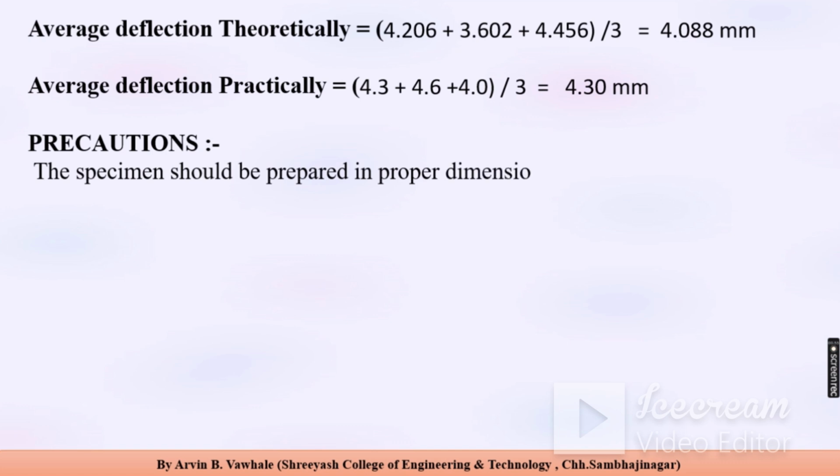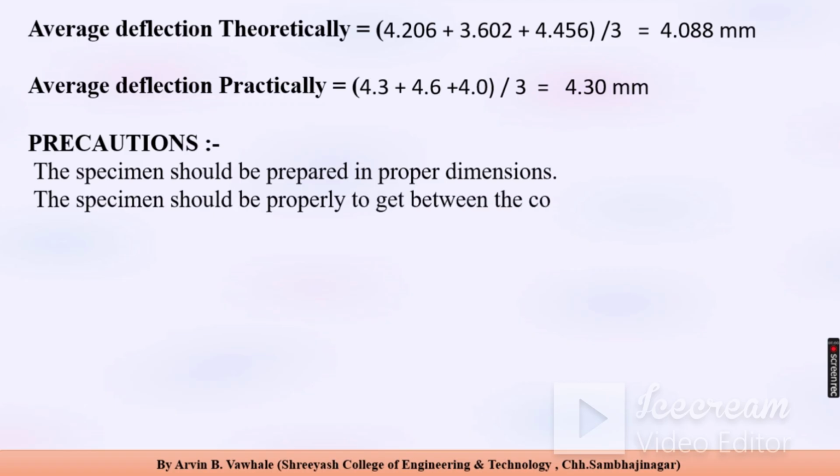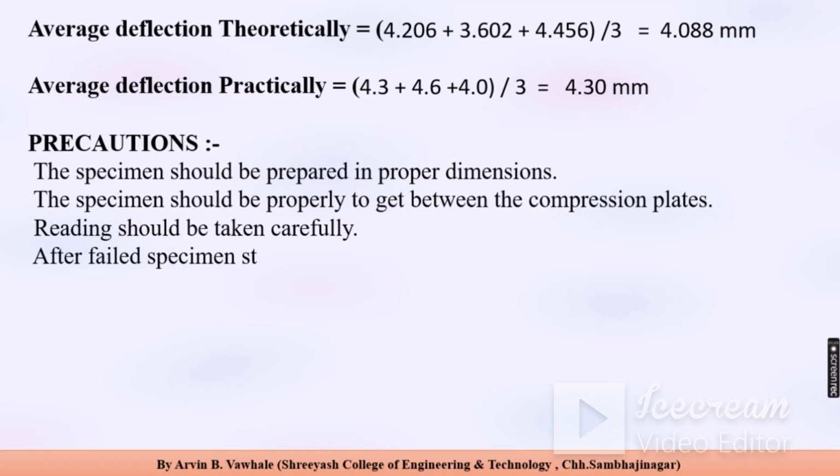Precautions to be taken while performing the practical. The specimen should be prepared in proper dimensions. The specimen should be properly placed between the compression plates. Readings should be taken carefully. After the specimen fails, stop the machine.